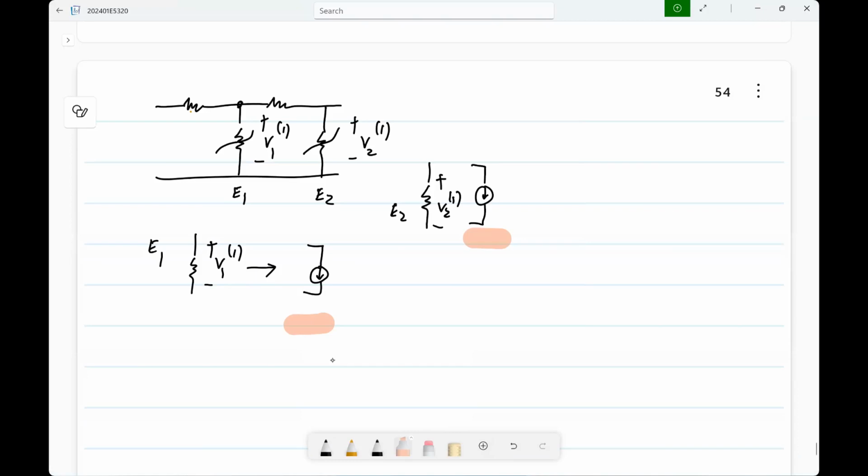No. At every step, what we are analyzing is only a linear circuit. Okay, we are just creating sources from the nonlinear characteristics. That's all. For linear circuits, superposition is valid. Yeah, that's right. But we have reduced the nonlinear analysis to linear analysis, stepwise linear analysis. This analysis, by the way, never gives you the correct answer until you go through infinite steps, right? Okay. So, it only gives you approximate answers, but it gives you a better answer than doing only the step one and then stopping. That's all.